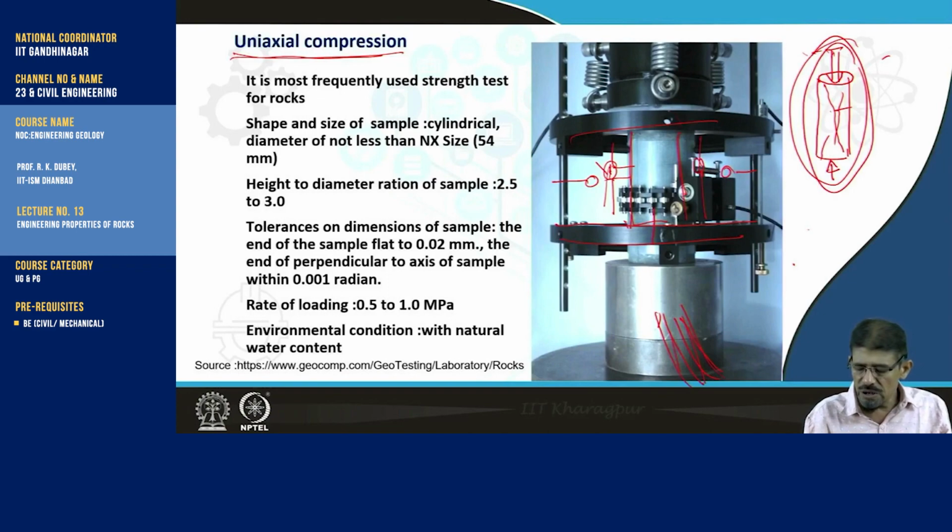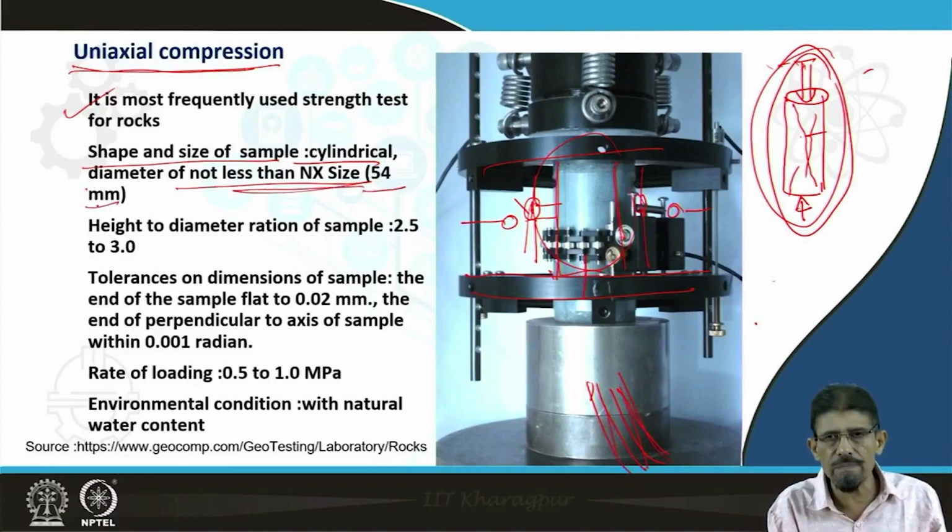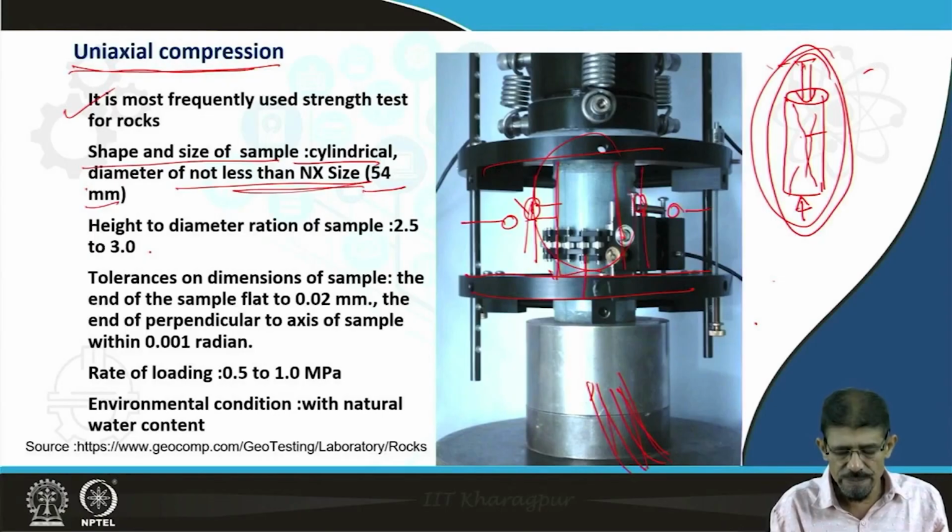For such testing, we have some simple specifications of importance. Shape and size: it is cylindrical, with diameter not less than NX size. This is the standard size, 54 mm diameter.